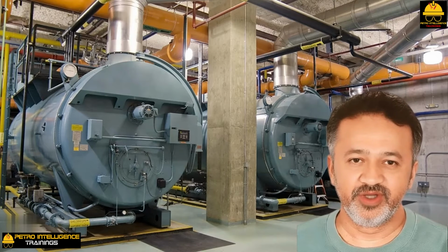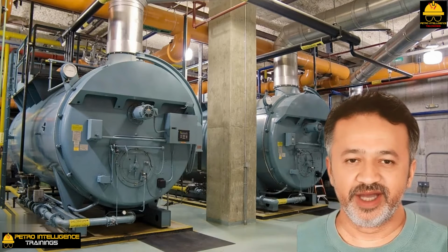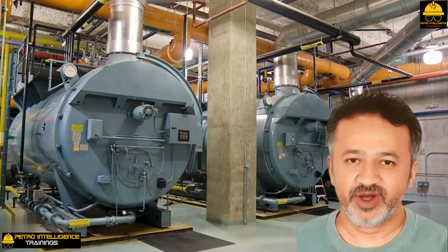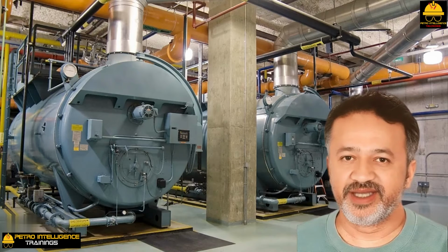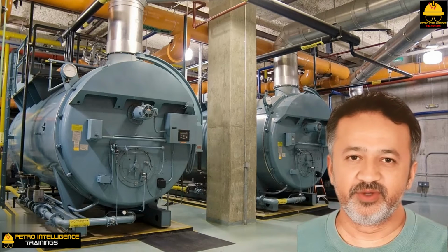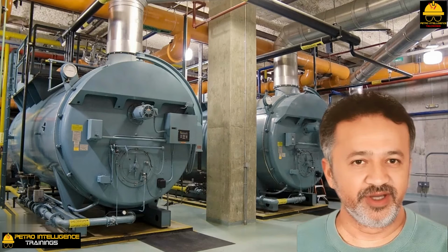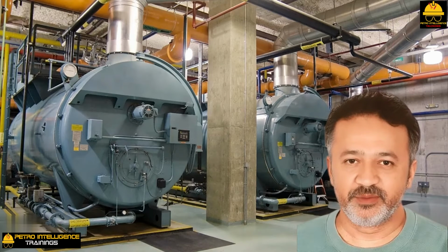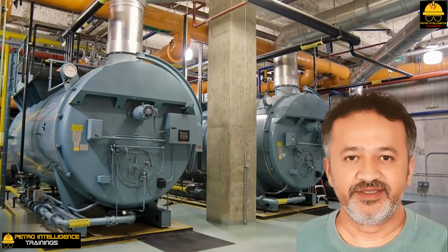An important feature of steam generation in a process plant is steam condensate recovery. This is usually a function of proper design of the steam condensate controls on individual steam heaters and reboilers, as well as proper design of the condensate recovery system. Experience shows a reasonably good condensate recovery rate in a large, complex refinery is 70%.